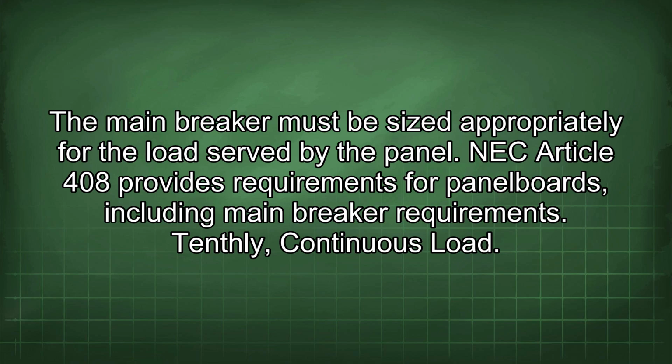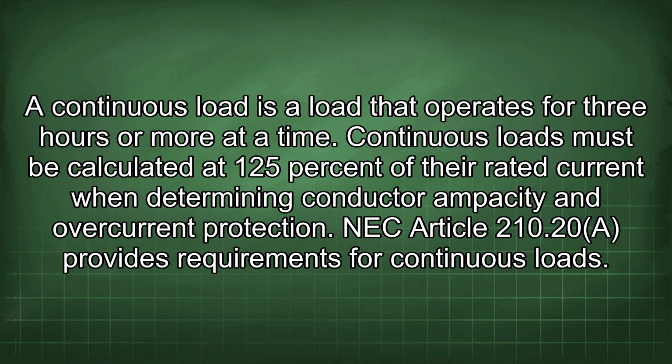Tenthly, continuous load. A continuous load is a load that operates for 3 hours or more at a time. Continuous loads must be calculated at 125% of their rated current when determining conductor ampacity and overcurrent protection. NEC Article 210.20 provides requirements for continuous loads.